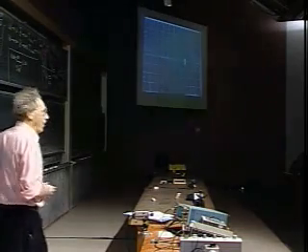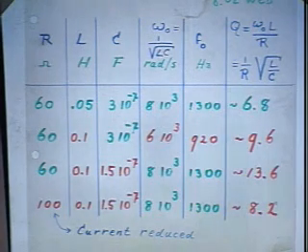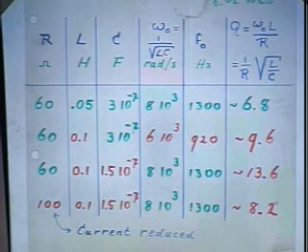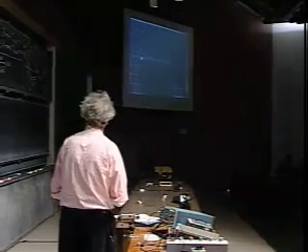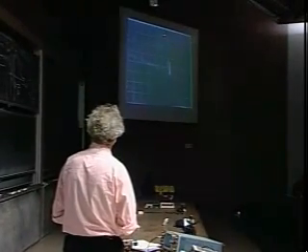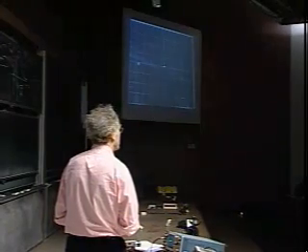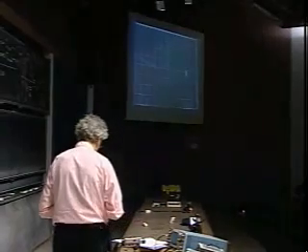So I have increased L by a factor of 2. I can bring it back to my original resonance frequency by now changing C. If you increase L by a factor of 2, all you have to do is decrease C by a factor of 2, and you're back at the same resonance. So I'm going to make C lower by a factor of 2, which I'm doing now. And if you look now and you have a good memory, you will see that the resonance frequency is back where it was. Again, V0 over R is not changed, and the resonance frequency is back here, even though L is now twice higher and C is twice lower.